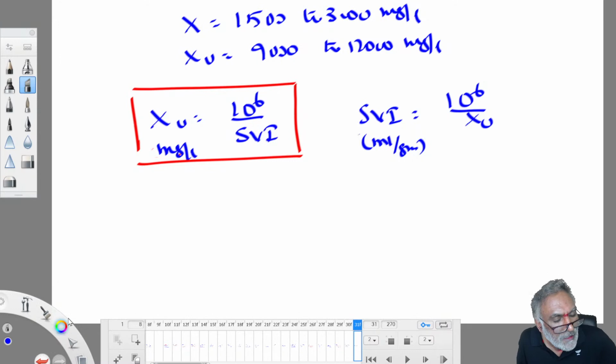If you want to design an activated sludge process system, these are the equations, so many you have to remember. This many numbers are there. Sometimes aerator capacity also they will ask. So total oxygen supplied by capacity of each aerator will give the number of aerators required, something like that. That much depth we will not go.